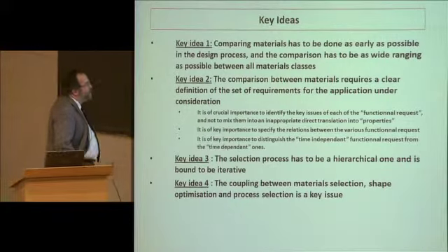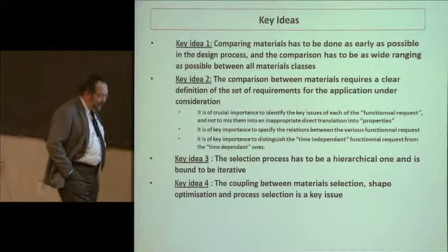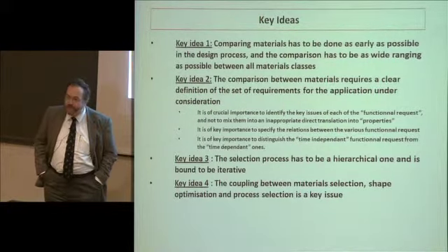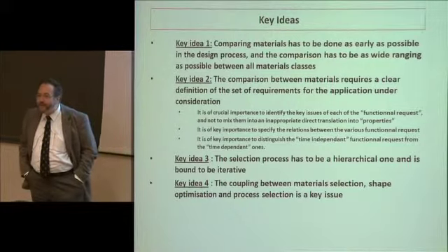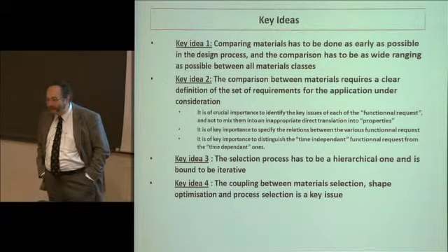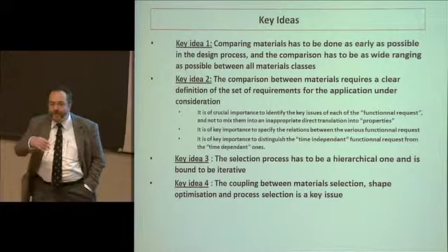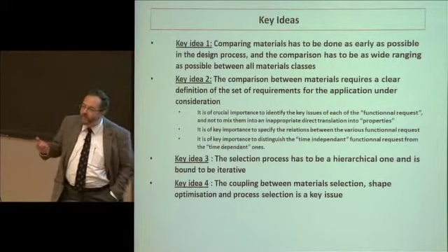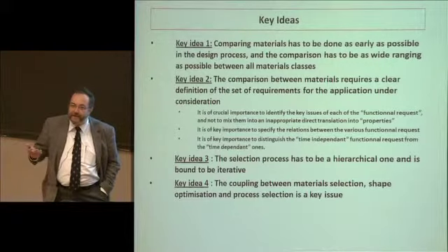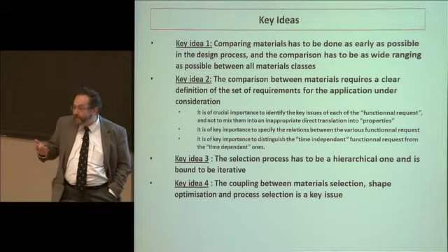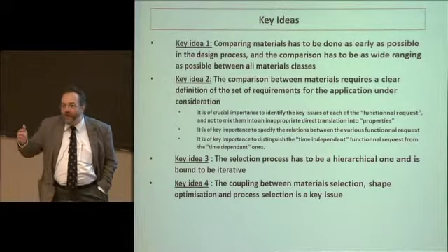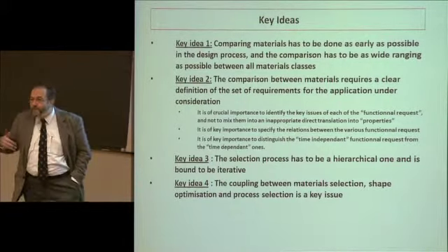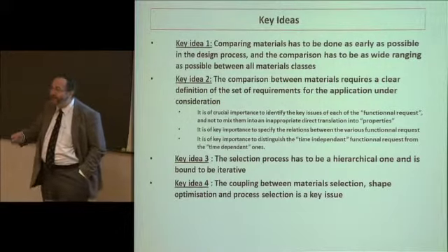And final point, a third point that's actually very important in the selection process: you must bear in mind that it's an iterative process. You have your specifications, you have a certain number of choices in your selection that are going to lead you to redesign part of the specifications and say, okay, I'm ready to give up on this as long as I can gain on that. So it's an iterative process.